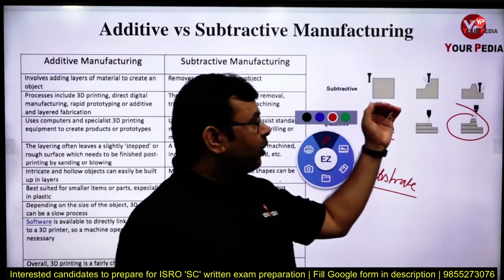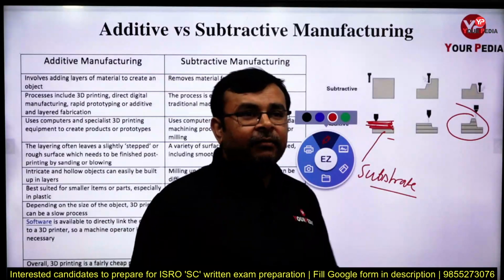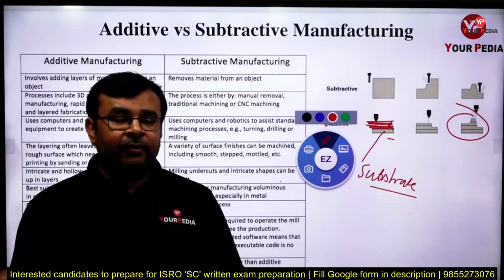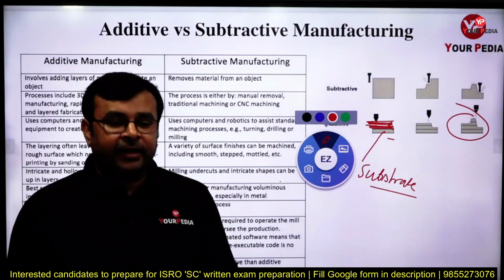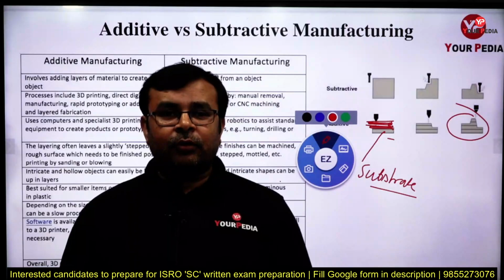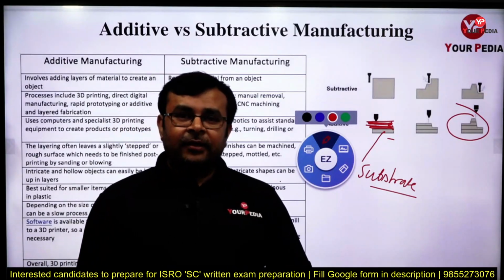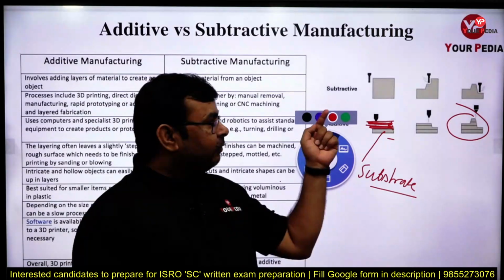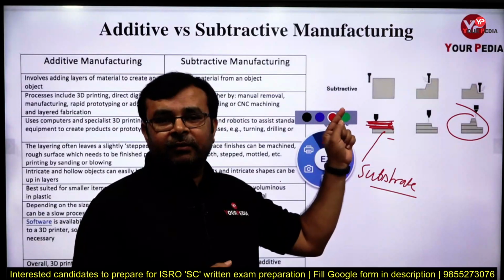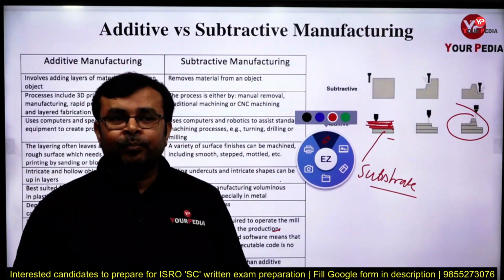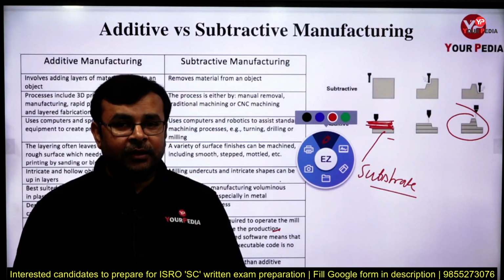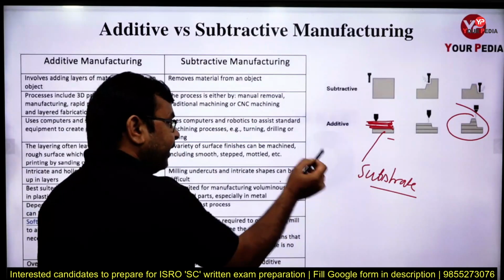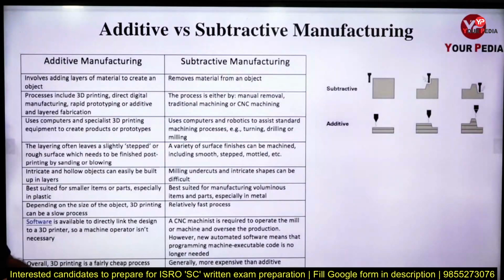And one more thing: sometimes we have very hard superalloys which are very poor in machinability, correct. So, it is very difficult to machine those materials to make a component. In that case machining is not a suitable process, correct. So, whenever we have a situation like this, with the help of additive manufacturing we can minimize or overcome these difficulties, and we can make the component, yes or no. So, this is one of the biggest advantages. And now let us see some more advantages.